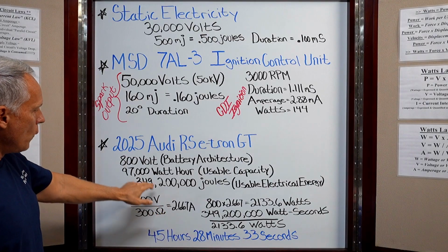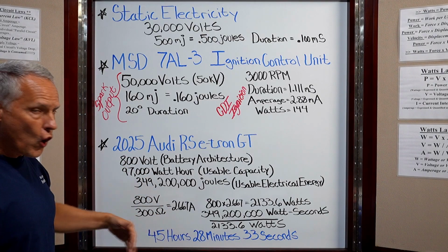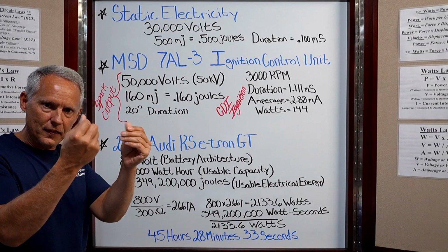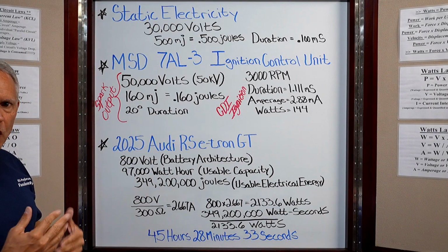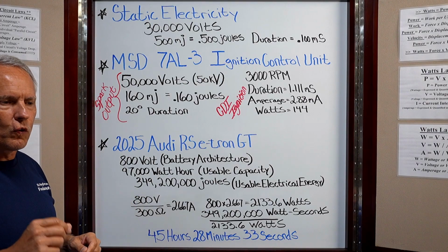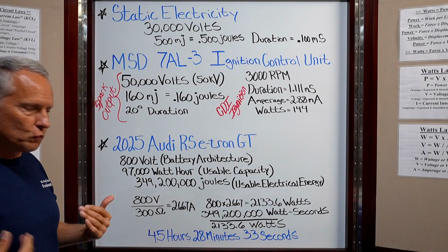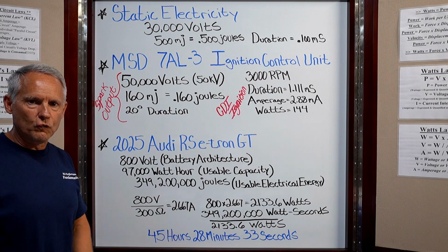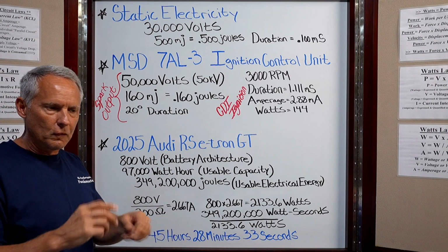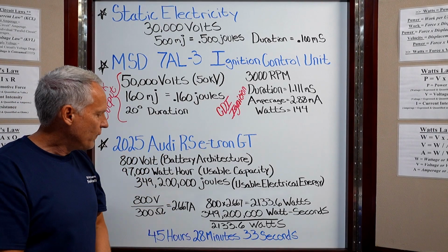But in this case, we have 800 volts of voltage pressure, and internally, once we get past the skin, our internal resistance is somewhere around 300 ohms. And 800 volts, in very short order, will penetrate the skin. Basically then you're left with your internal resistance, which is 300 ohms. This is just a rough calculation. I didn't look this up anywhere. I just took a pen and paper and figured it out right quick.